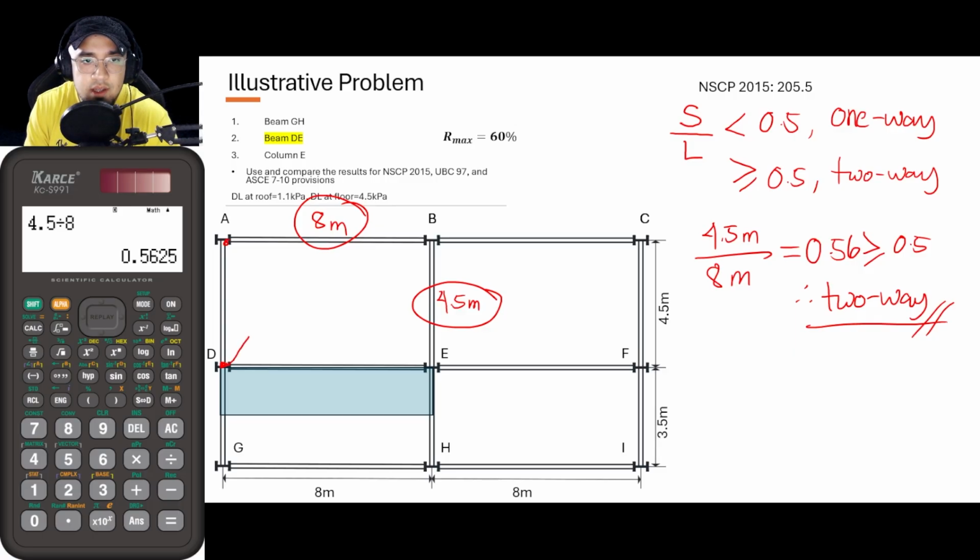So suppose that this is that 45-degree line, assuming that my drawing is correct, which is not, by the way. If you draw 45-degree lines here, that triangle is now the tributary area of the beams along the shorter spans. And from that, guys, ito na po yung kanyang tributary area.